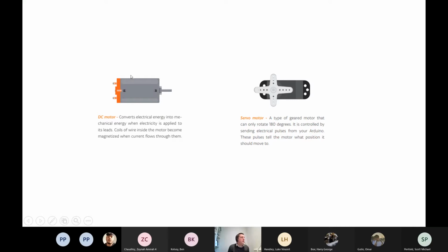So we'll come back and think again about DC motors, but importantly, we've gone from talking about resistors, which were pretty useless, to talking about motors, which are much more useful, but they all fit into circuits in very similar ways. A servo motor is a different kind of motor. Rather than just spinning and spinning, you control the position of it. On model aeroplanes, for example, you might want to control an aerofoil so it can just lift up through a range of about 30 degrees. That's an excellent task for a servo motor.